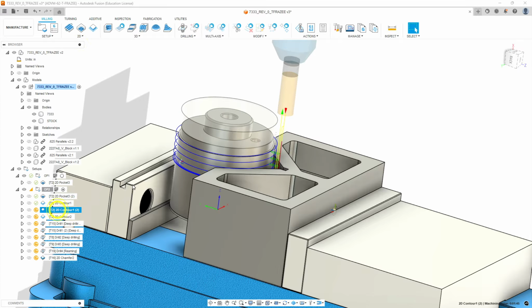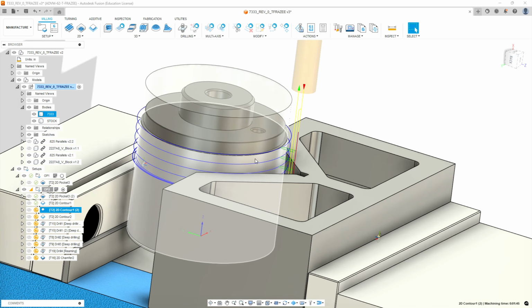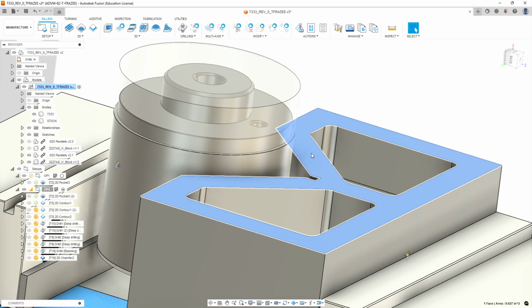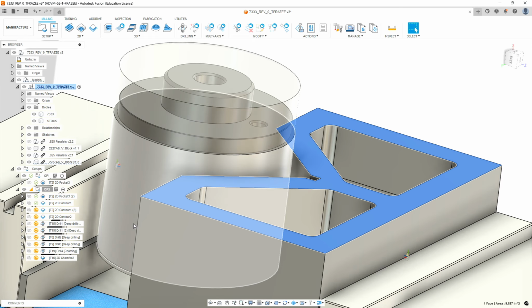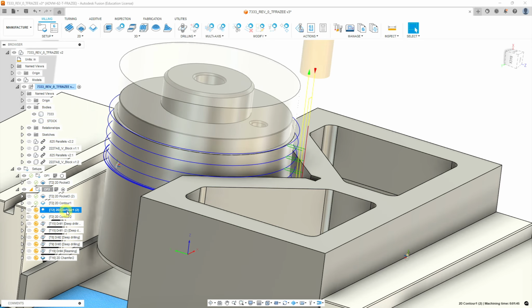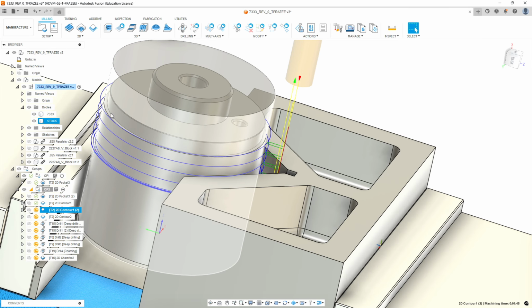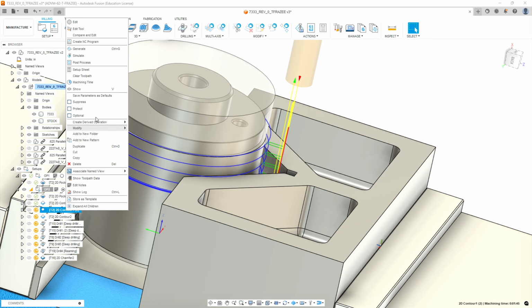Okay, what does Op 3 do? Now Op 3 goes around the outside. Well, we don't want to keep that. See how that's cutting right into that steel jaw? It also is taking off more on the radius than we need for this. We don't need to rough this. It's a little tiny step here. I think it's only a 60th per side.